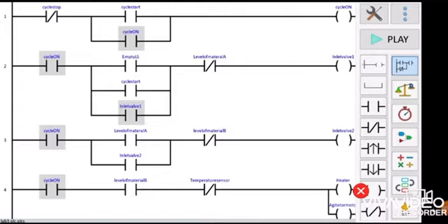Today I'm going to present lab 3 on how this ladder diagram operates. This diagram represents an automatic tank system which consists of two materials, material A and B. This diagram consists of three level sensors for the detection of both the materials and the entry level. It also consists of heaters and temperature sensors. The tank operates in a way where when both materials are accumulated in the tank, the agitator motor will run until a predefined temperature is reached.